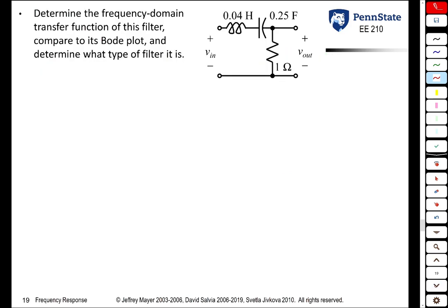So how do you get band pass and band stop filters? Well, now you need more than just a resistor and a capacitor. You need to add an inductor. So let's look at this circuit first. We have an input signal, Vin, applied to an inductor, capacitor, resistor combination. We have the inductor and the capacitor along the top branch and a resistor on the right branch. And we're measuring the voltage across the resistor.